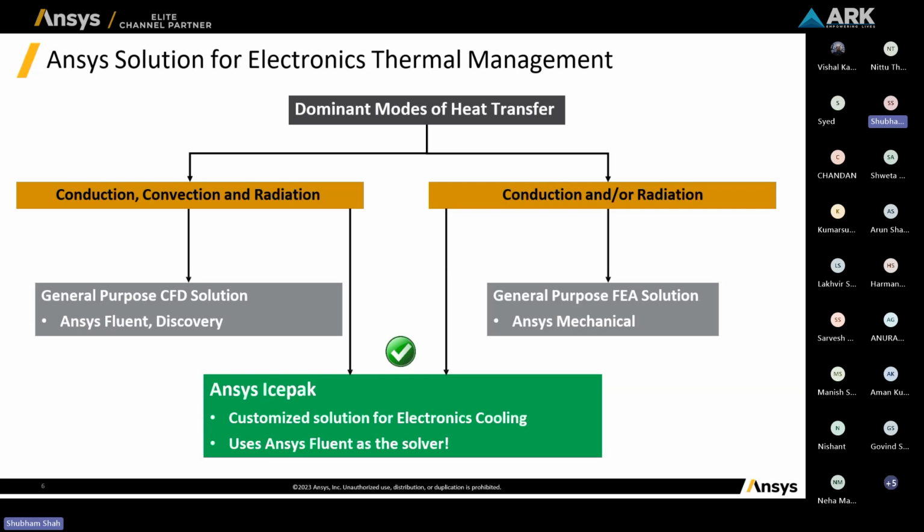Let's say you have a component, for example a CPU. Your CPU is kept in some hotter, warmer area, not in a regular air-conditioned room, and it is exposed to the open atmosphere. In that case, you may want to include radiation, to see how heat is gained through radiation. If there are direct sun rays, it's obvious that the system will heat up faster compared to a system kept in a cooler environment. So this kind of radiation can also be included while working in Icepak and Fluent.